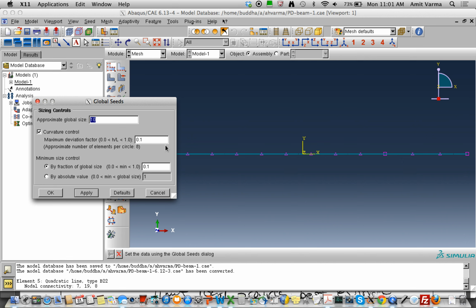Now, what do I mean by robust solution strategies? We never talk about that in class. It would be something that would get covered in your advanced finite element class. Even in your basic finite element class, we don't really talk much about solution strategies. In your basic finite element approach, you've got F is equal to K delta. Is that right? Elastic finite element analysis. So delta becomes equal to K inverse times F.